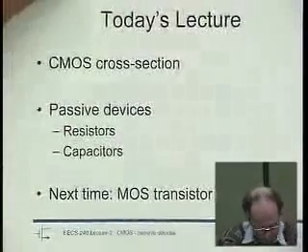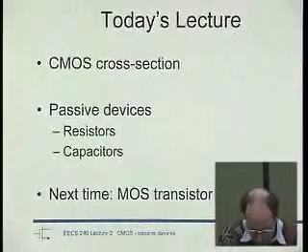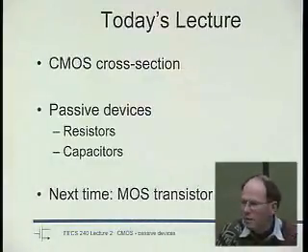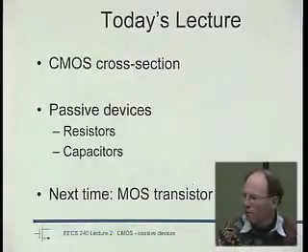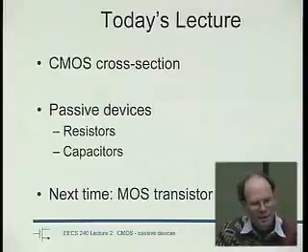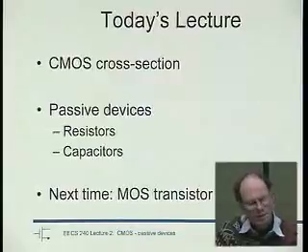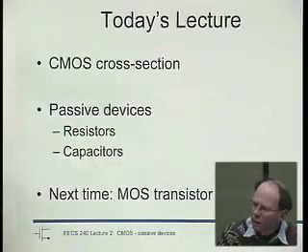Okay, so now, in order not to get too deep into all these challenges and so on, we'll start a little bit easy. We'll start first with the CMOS cross-section. I find that extremely helpful to just know what the heck is actually all the stuff that is there. Right? SPICE is always very nice. Before, I called SPICE a relatively low-level simulator, but it still abstracts a lot of stuff away, right? And so the CMOS cross-section very often is a good thing to think about.